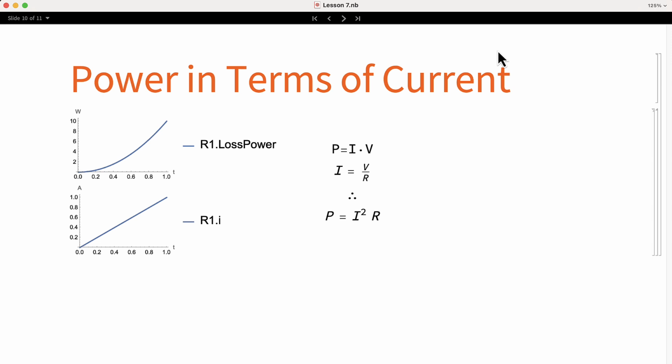If we take Ohm's law and we write the equation of the power in terms of the current and resistance, we can see that there is a nonlinear behavior. The power increases quadratically as the current increases. We can see in the simulation how drastic the increase of power is as the current increases. For that reason, electric systems that require a large amount of energy are fed with a power supply that has a high voltage in order to reduce the current and decrease the losses.